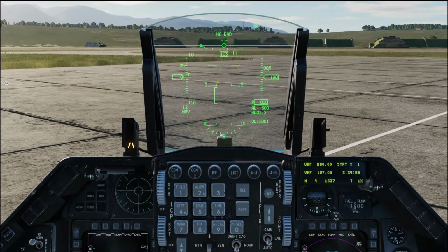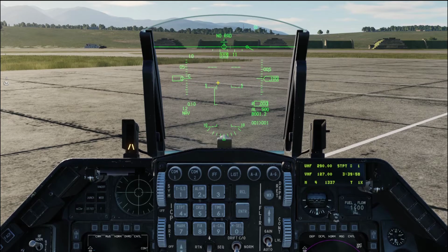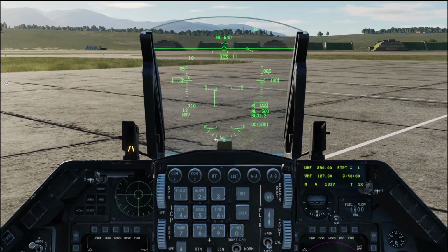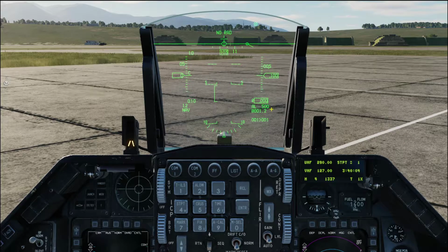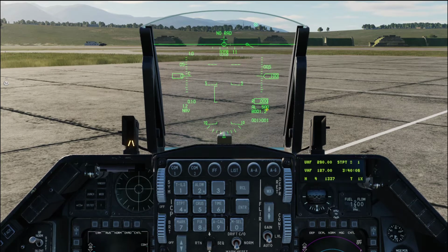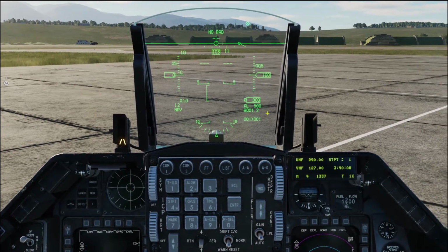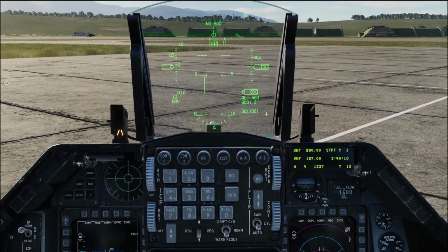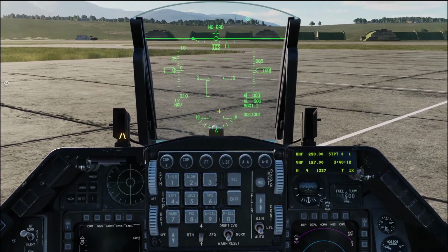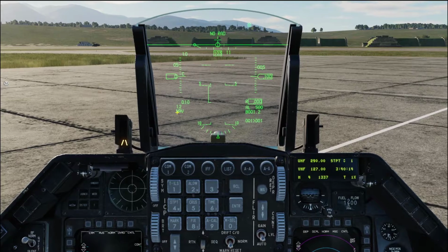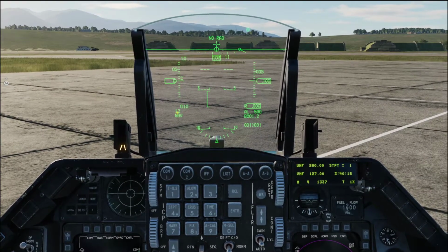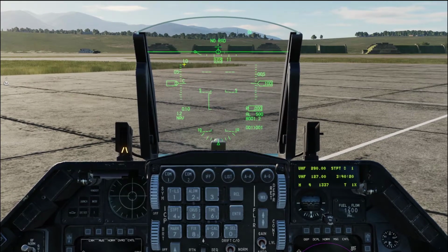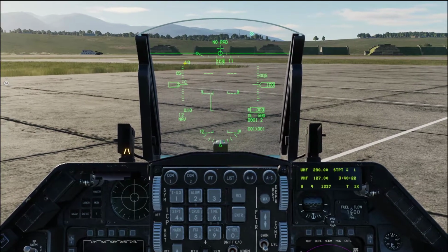In the bottom we have the roll indicator. Towards the bottom right we have the radar altimeter height, the altitude low settings as fed into the DED, the distance to the selected station, and the current steer point. Towards the bottom left we have NAV written, indicating that right now NAV master mode is selected. On top of the speed scale, 1.0 indicates the current G's of the aircraft.